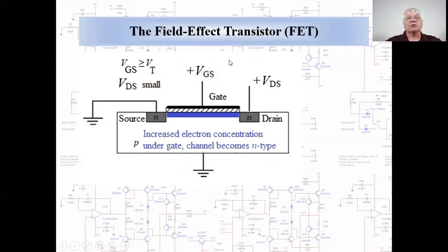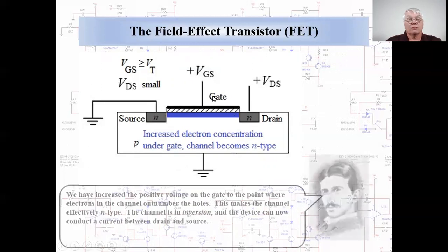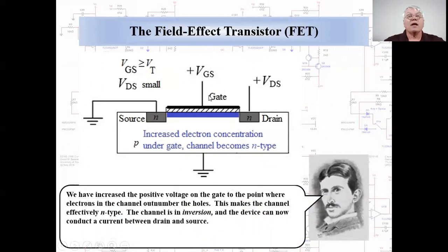The threshold voltage is the gate voltage at which the channel enters inversion. Now, one note, this shows the case in which the drain voltage is relatively low. This is an N-type transistor which conducts current by means of electrons in its inverted channel. It is called an NMOS or N-channel MOS device. Note that the NMOS device is built on a P-type substrate.